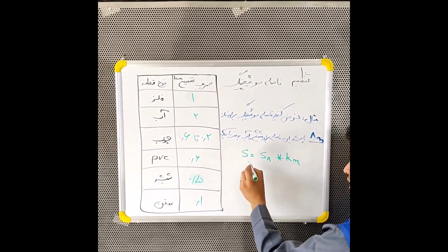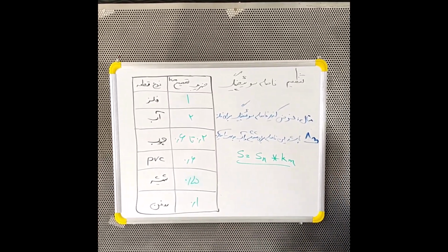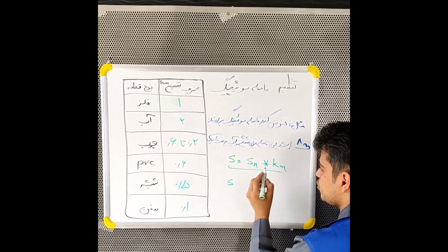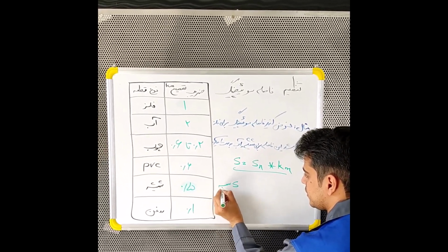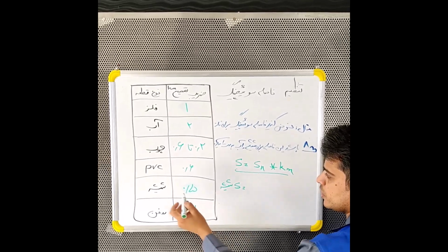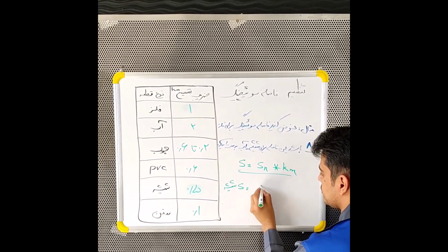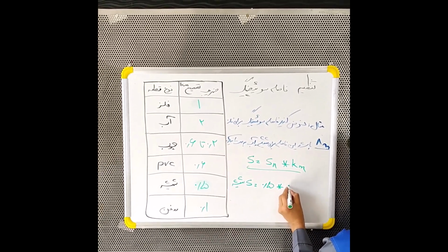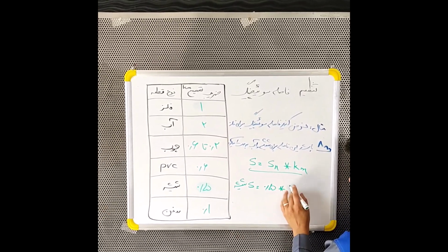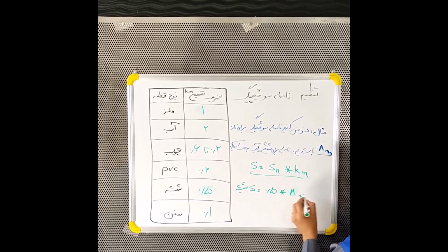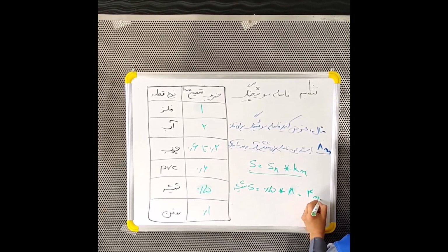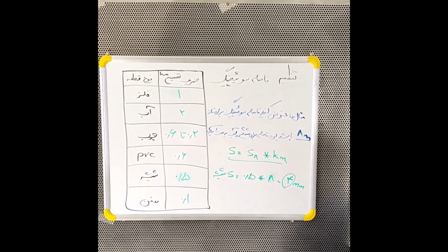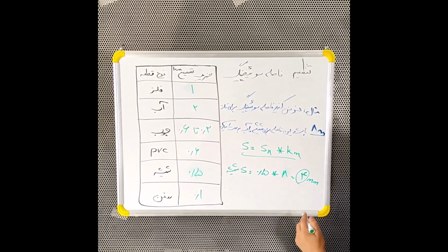You should use this formula for other ingredients. The detection distance for glass is equal to, we enter the glass, so the fraction is this section, and multiply by 8 millimeters, which is equal to 4 millimeters. Therefore, the maximum distance for glass detection is 4 millimeters.